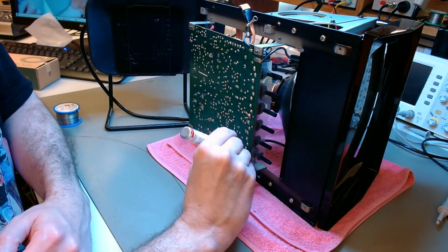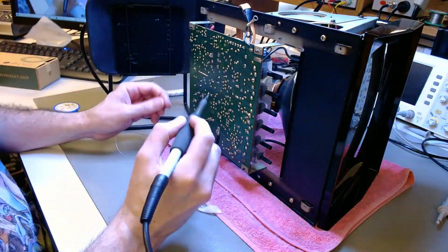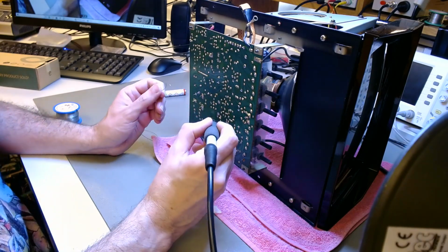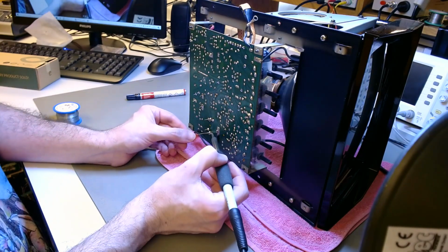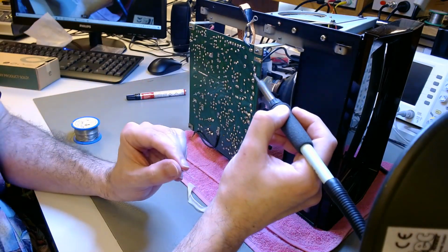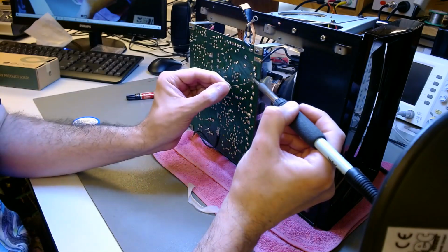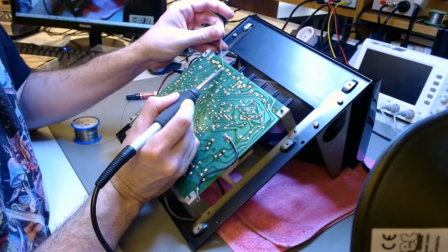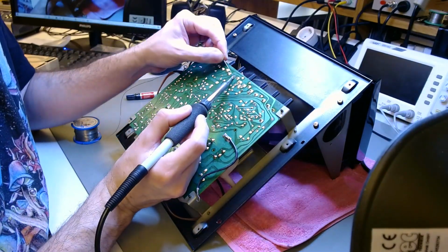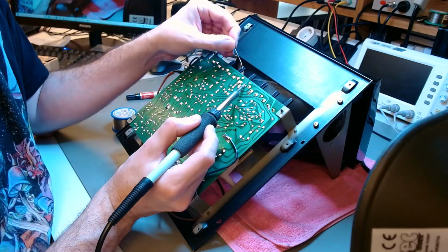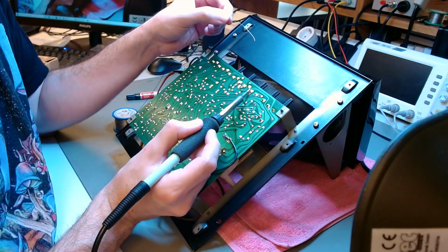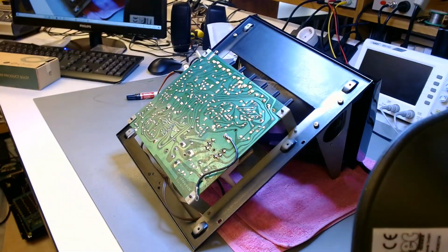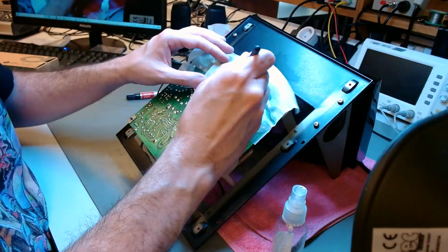But since I have the soldering iron hot already, I decided to reflow some joints. Somebody on Twitter reminded me that the flyback usually vibrates a lot, and if the solder joints are old, they can crack. They are all working right now, but since this is a restoration, I'm going to prevent a future problem by reflowing the solder joints of the flyback, and I'm reflowing the solder joints of all the tuning potentiometers of the monitor. I forgot to do that last time, and sometimes when I tune the image, the image falls out for a fraction of a second, which is characteristic of a dry, broken solder joint. So I reflow them all, clean it all up.